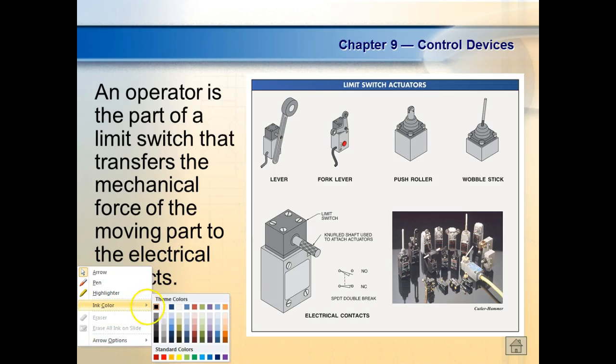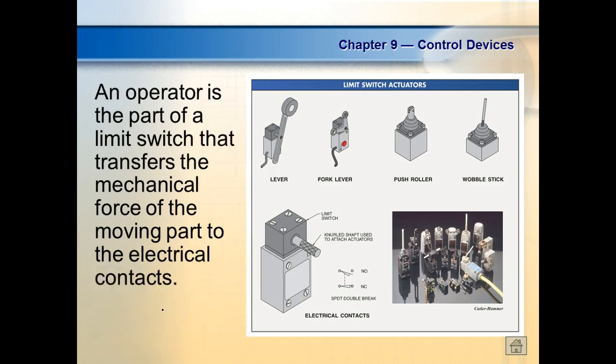Now we're gonna start putting symbols on tests, because this is one of the things you gotta learn in this class, is learn the symbols, right? So what's the symbol for a limit switch? Normally open. So we start off with 2 dots, and we're gonna come over here. If it's normally open on these switches, we're gonna draw it down, right? And then we're gonna put something on there that indicates it's a limit switch.